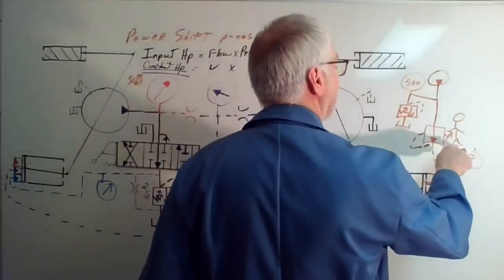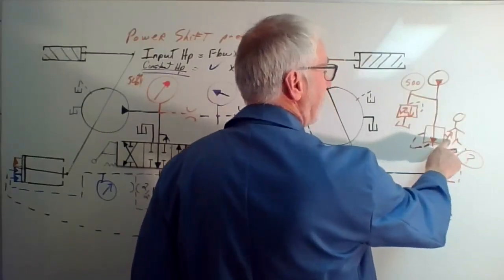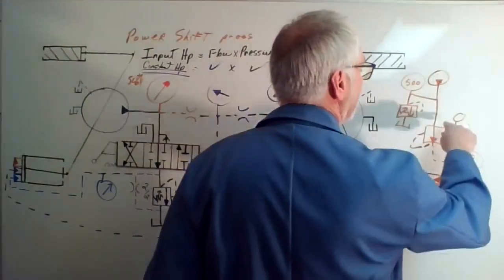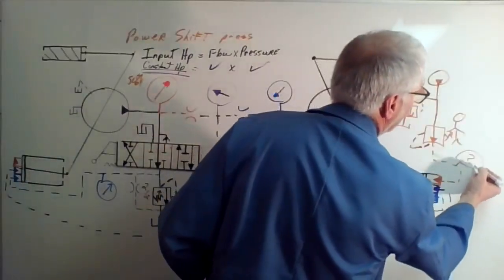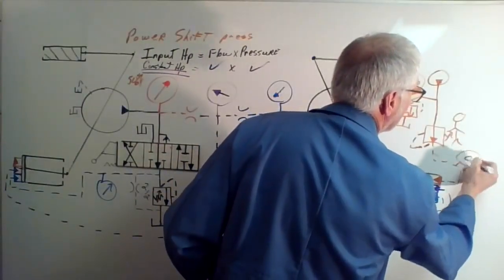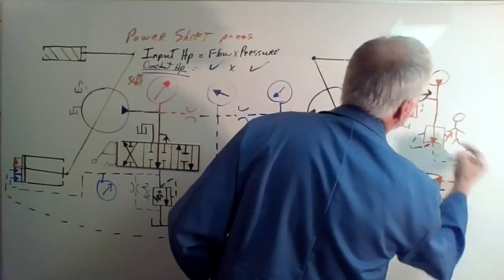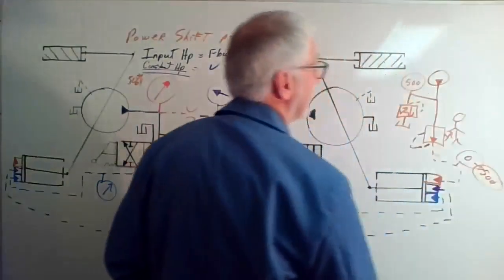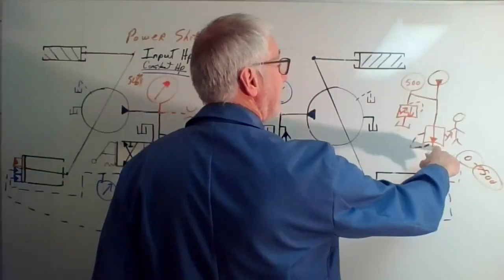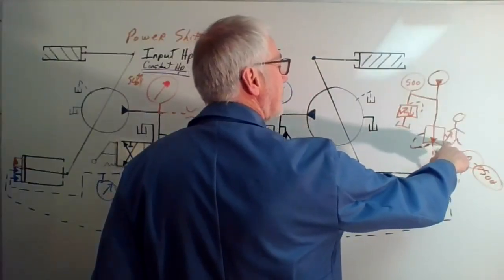And if I can control that pressure by controlling the spring force, then I can either have this go up or down. I could have potentially 0 here, or I could have all the way up to even 500 psi downstream of this valve, all with operator control.